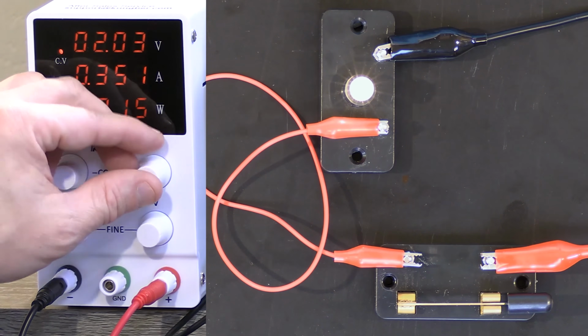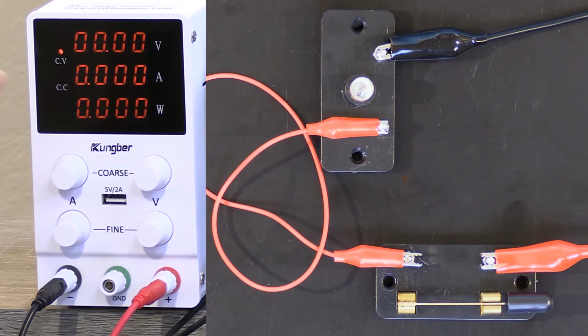This light bulb has a higher resistance. It's not something we've measured yet, but we know it has some sort of resistance, and that's why it's heating up, because the resistance is so high. It's like an internal friction going on there. So voltage is the push, current flow is the flow, but anytime current flows, it flows through a resistance, right? Every material that you're going to work with on a daily basis will always have some non-zero resistance. The only thing that doesn't is something called a superconductor, and I'll show you a demo of that another time. I already have the superconductor, I just need to film it. It's a special material that has a quantum effect that has zero resistance. But in everyday life, every material you ever deal with will always have resistance. So as we go up and down, we get more and less current, and of course, the power delivered as well.